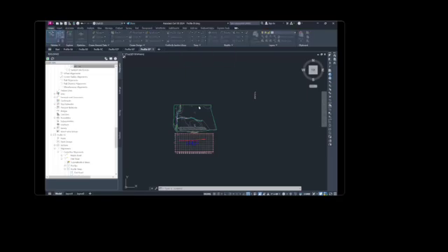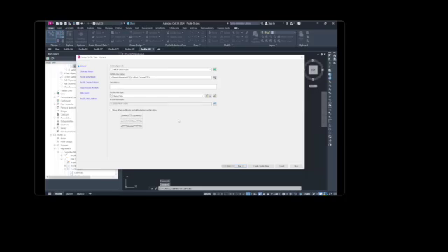In the wizard, we're gonna select alignment north south road, show offset profiles by vertical stacking profile view selected. The graphic at the bottom of the page changes color to indicate that the option is active. Good. Then on the left side of the create profile view wizard, click stacked profile,